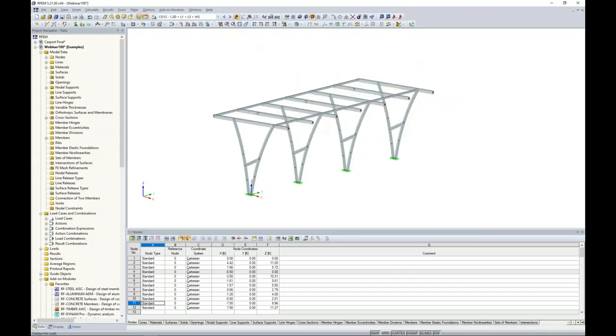Now, before we are ready to run our analysis, there is one thing that I want to discuss from the ADM, and this is the stability requirements according to section C2. So I actually did a previous webinar around 2 years ago, but everything is still applicable to design today, according to the ADM 2015. And I went into much more detail about the stability requirements in Chapter C. So certainly refer to that on our YouTube channel or on our website. You can just search ADM and that will bring up that previous webinar.